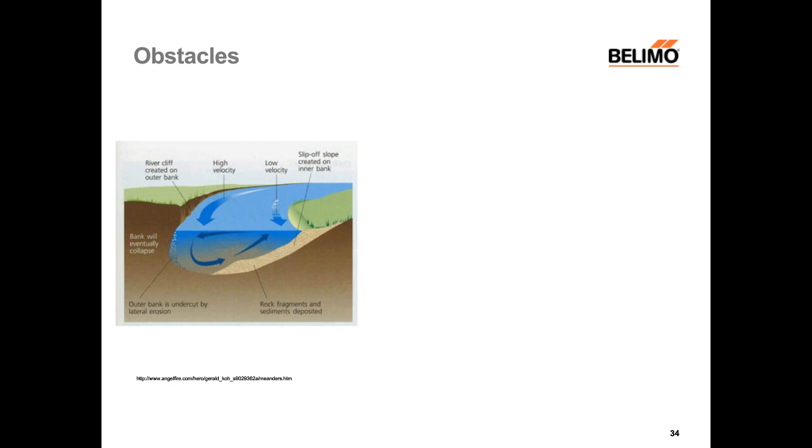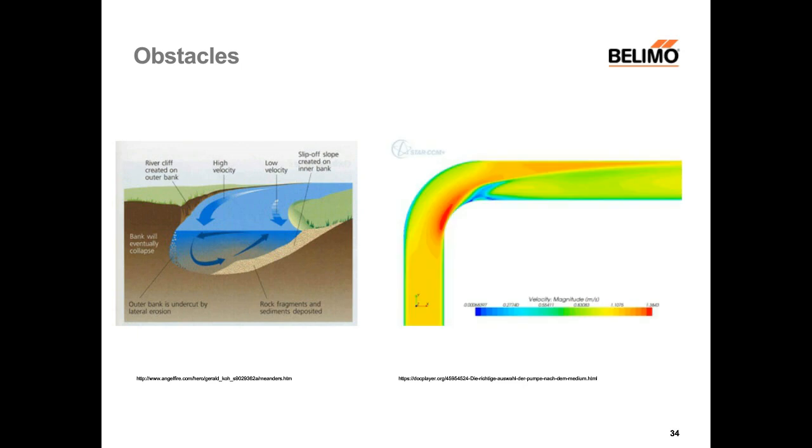Now, exactly the same thing happens within a pipe. Most of the water just follows the outer wall and is therefore getting faster, and it's slower on the inside. Therefore, we get a misshaped flow profile after the pipe bend. Other causes for misshaped flow profiles can be, for example, temperature sensors or other inserts into the pipe, valves, T-splitters, and so on.